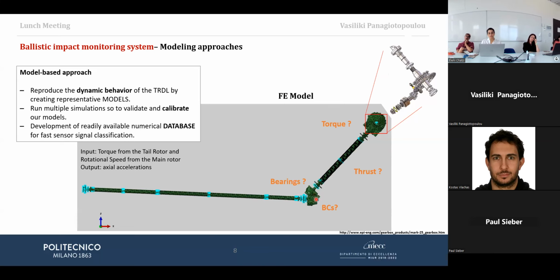In this case, the case of the gearbox is just fixed to ground, but in reality it is fixed to the tail frame of the tail boom, which might experience some bending loads, so it might not be a good assumption. Then the bearings are simulated as rigid constraints, which is actually not true, of course.